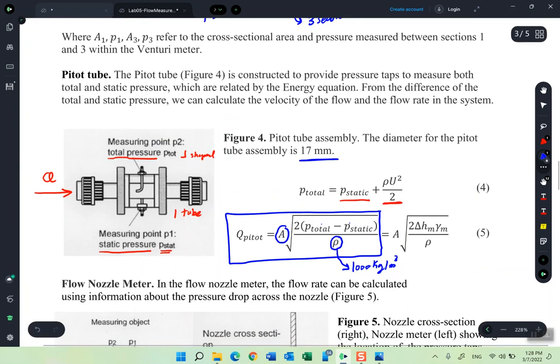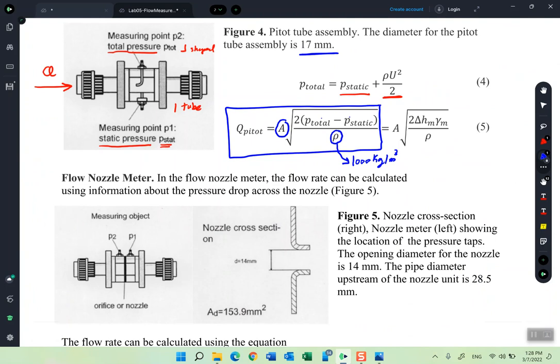Great. So, do you have any questions about how we can measure the flow rate from the Venturi tube? I mean questions about the concept itself and about the experiment. So, any questions? In this case, we don't have a change in the diameter. It's the same. The diameter is the same. The only difference is that you are getting two different types of pressures. There is no change in area.